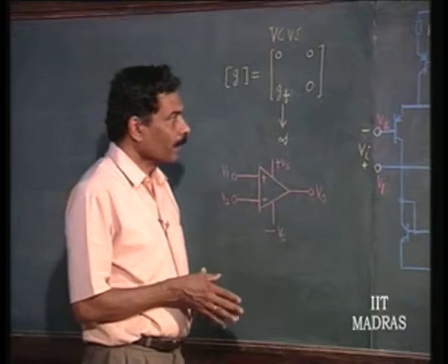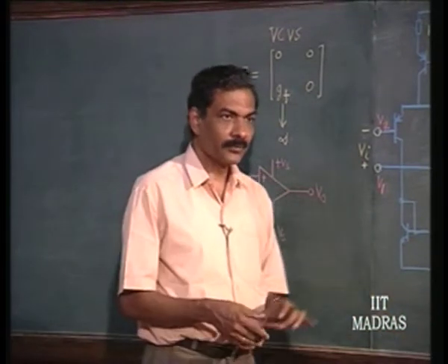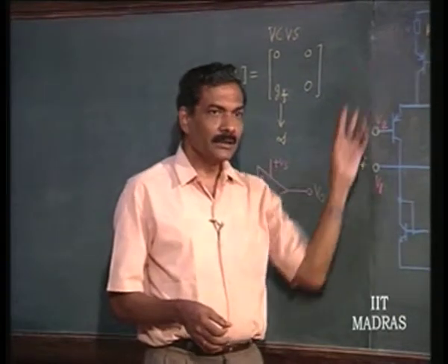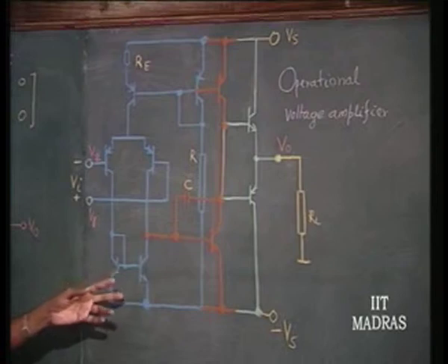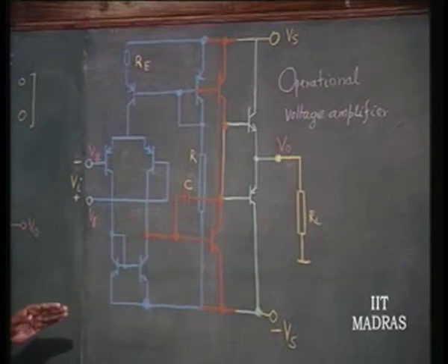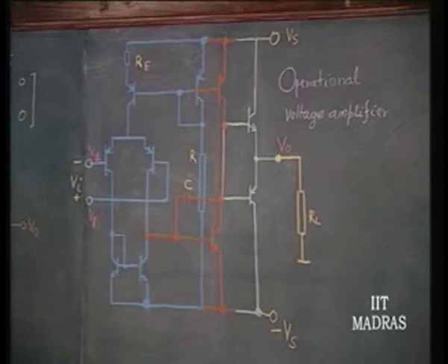Now, let us consider the input stage. We already have obtained this structure for a differential amplifier without using any resistors. So, this differential pair, in this particular case we have chosen it to be PNP transistor, assuming that in a given technology, we have good PNP transistors available, we would select that.